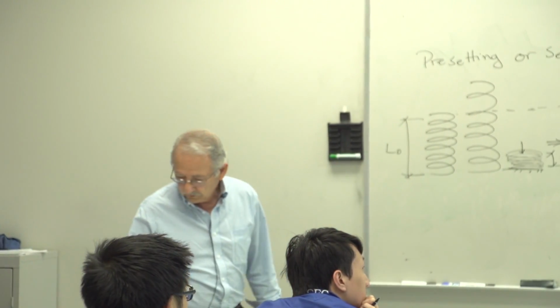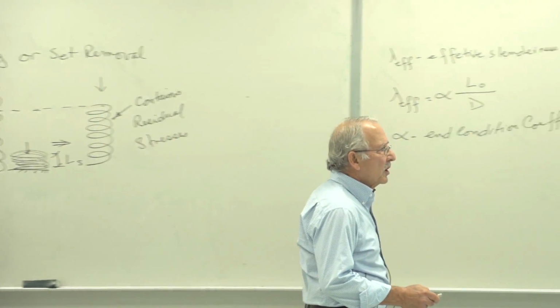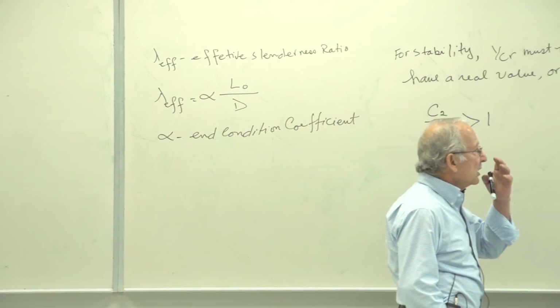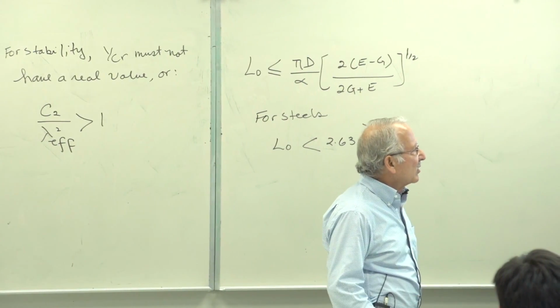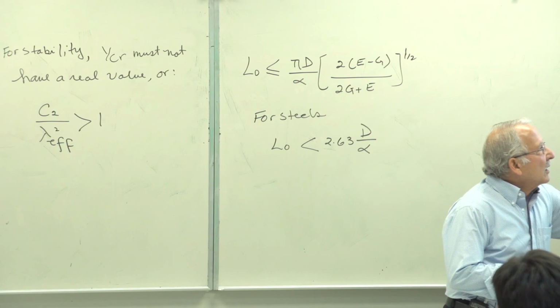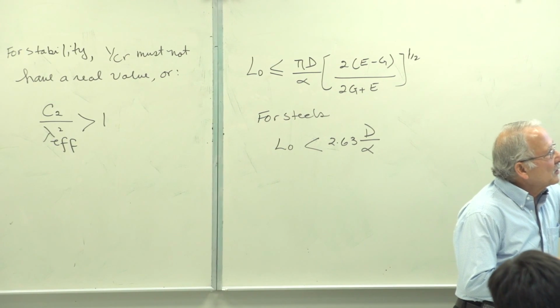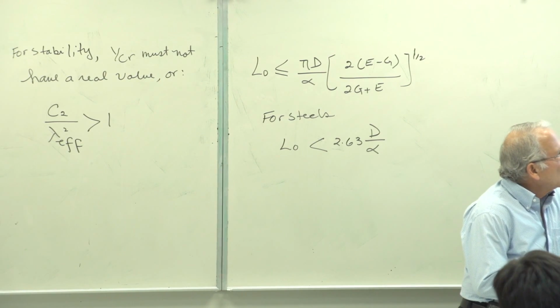Take a look at this table. There's the material. Music wire is one of the main materials that we use for springs. Most materials for springs are very high strength. Maximum percent of tensile strength, that's your maximum allowable torsional stress.